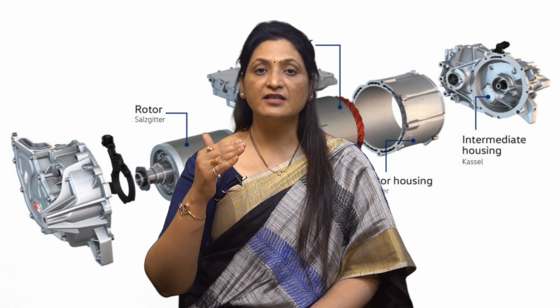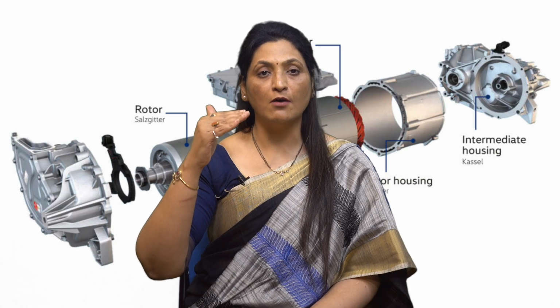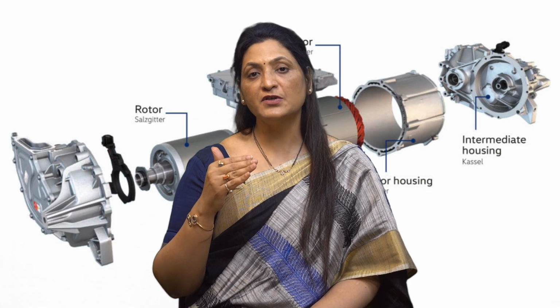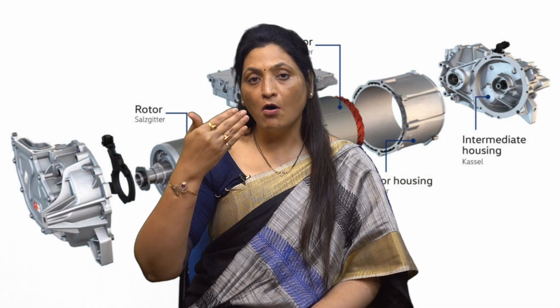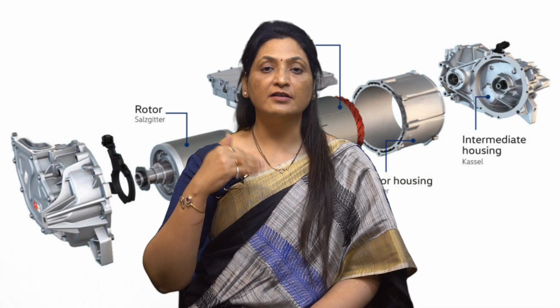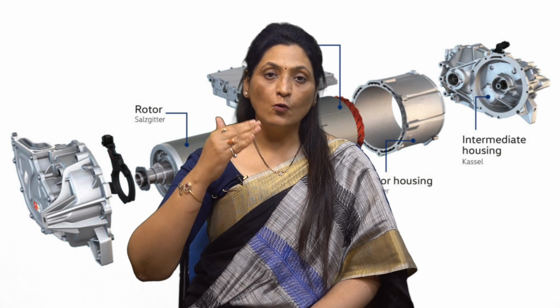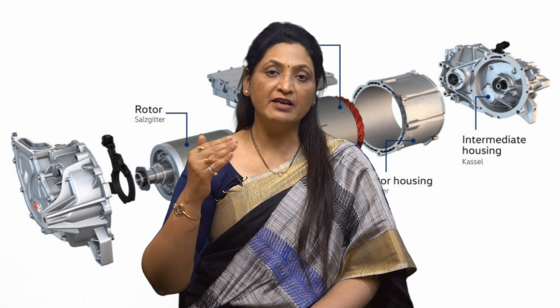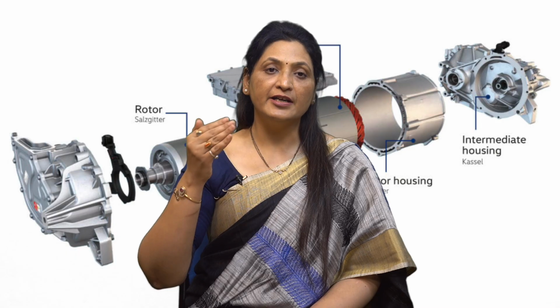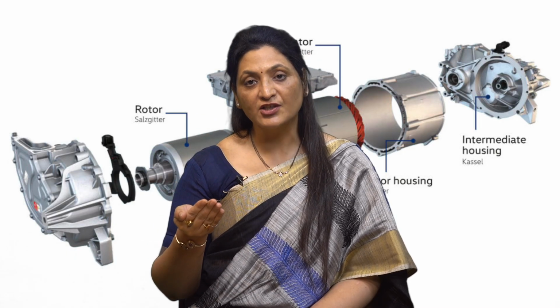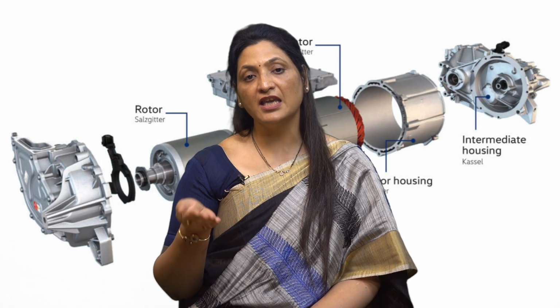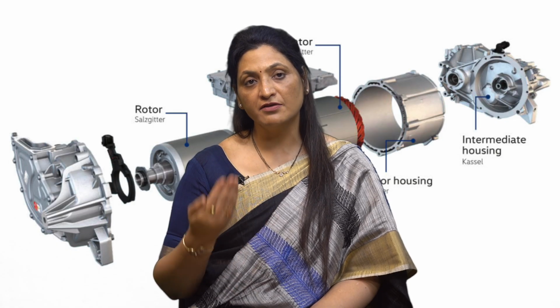For instance, during the upward movement of a load or compression of a spring, the potential energy increases and the torque opposes this action. Conversely, during the downward movement or spring release, the potential energy decreases and the torque facilitates the action, maintaining its direction even if the drive's direction reverses.